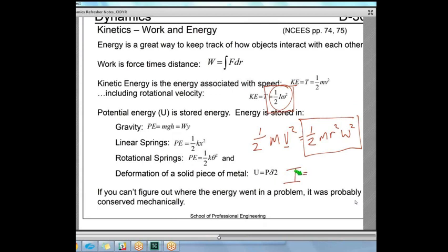The mass moment of inertia of an object is the mass of that object times the radius squared of the curve you're spinning it around. Mass moment of inertia tells you how difficult it is to get something spinning in the same way that mass tells you how difficult it is to get something moving in a straight line. So as we translate these things, our m becomes an I because our v squared became an omega squared. And as we kind of showed, the r's all cancel out, and this translation does work.